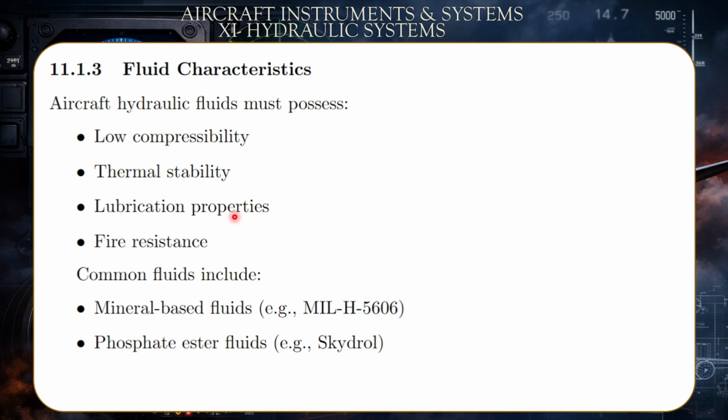Lubrication properties. Fire resistance, so they should not inflame due to heat. Lubrication means they flow freely within the pipe without sticking, so low viscosity. Common fluids include mineral-based fluids and phosphate ester fluids, which is Skydrol.